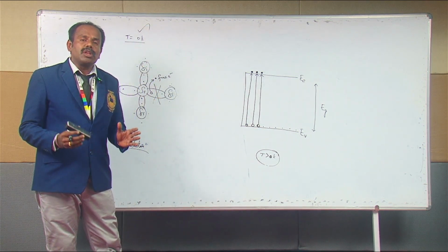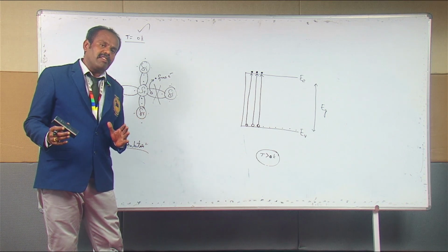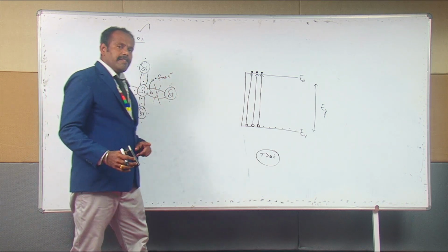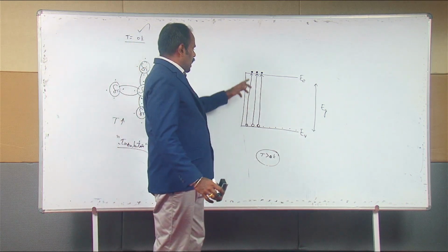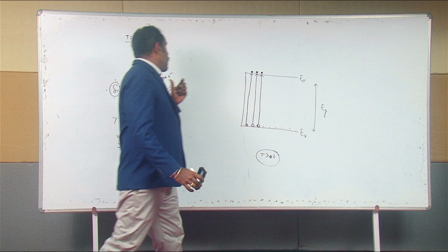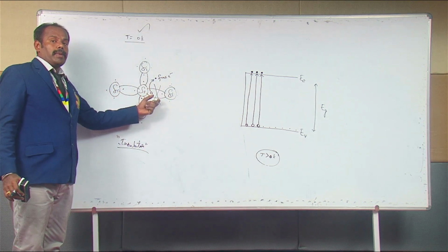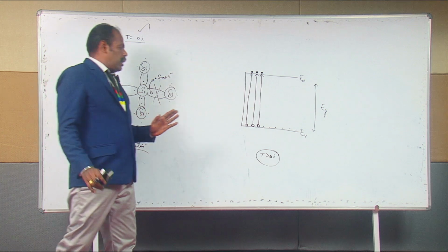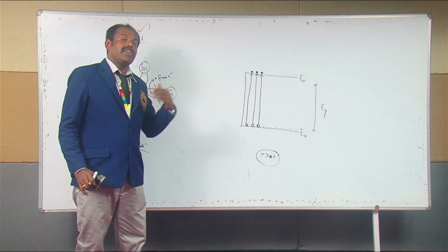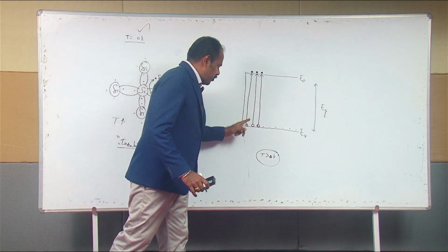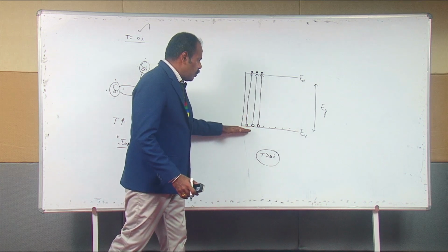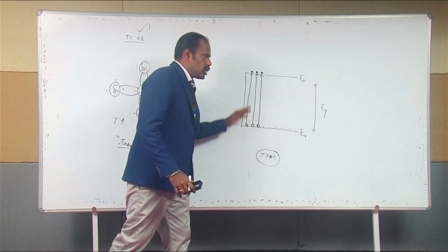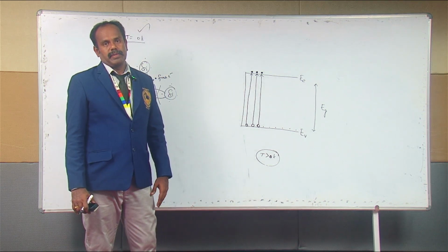As long as we increase the value of temperature, under the influence of the temperature, all these electrons which were previously encased in the covalent bond formation will break the covalent bond and be set as free electrons. When they become free, from the valence band they make the transition to the conduction band.